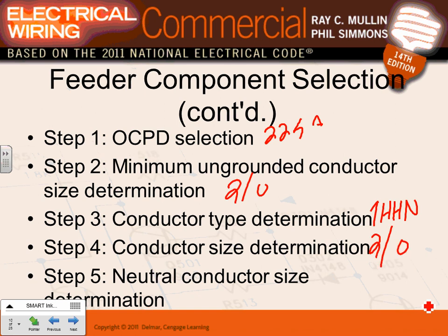Neutral conductors, as it said, guys, I always say match the overcurrent protection device up to 200, say, and 250 amp. In the 225 all the way to 300, match the overcurrent protection device. After that, we start the rate based on 2 factors: either the actual neutral load, or if I don't know the actual neutral load in the panel, what do you do? 70%, like you guys have done with me. 70%.